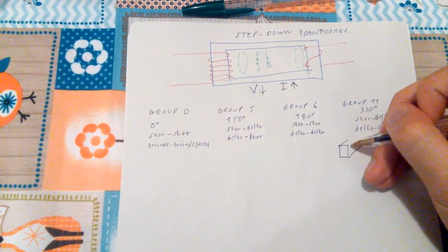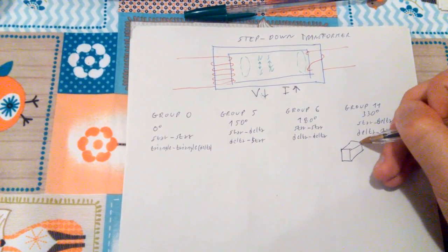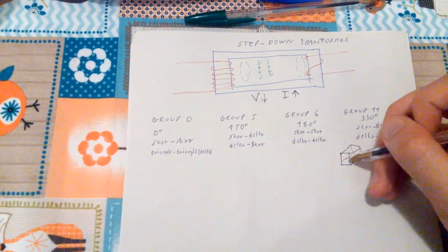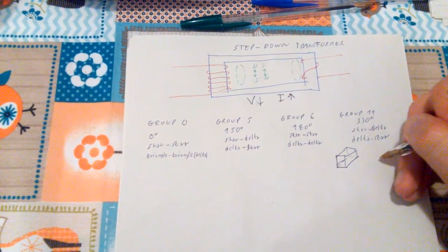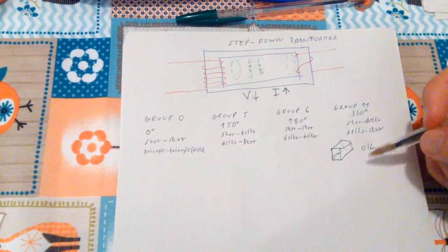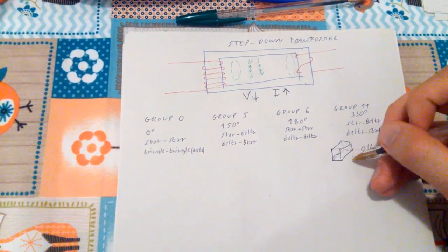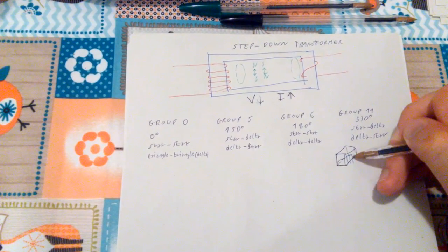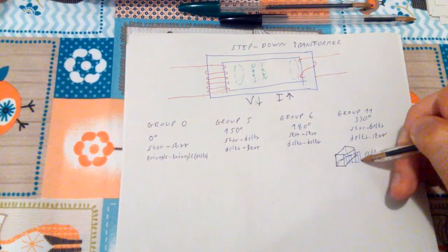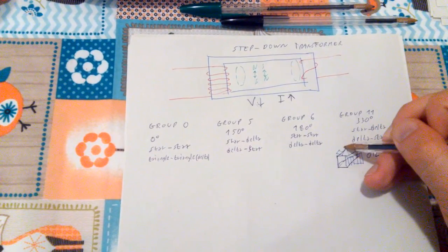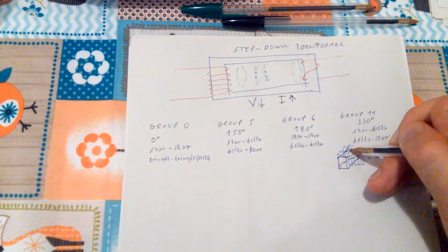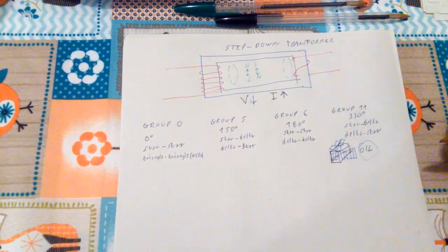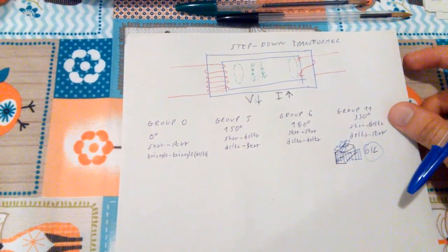And inside this box you are basically gonna have oil. They're basically gonna be cooled down using oil, and then something to dissipate the heat, because there's gonna be a lot of heat inside the transformer, so they're submerged into the oil.